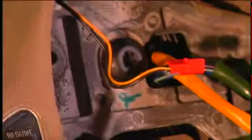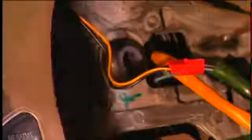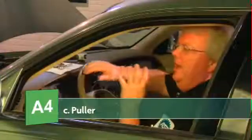Now we've got the steering column. Now we've got to figure out how to get the steering wheel off. And on this particular Ford, we've got one big bolt with a Torx fitting. That's going to be removed, and then we're going to get the puller out and pull the wheel.